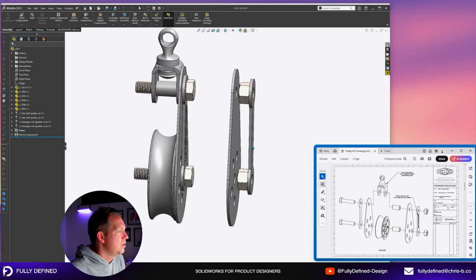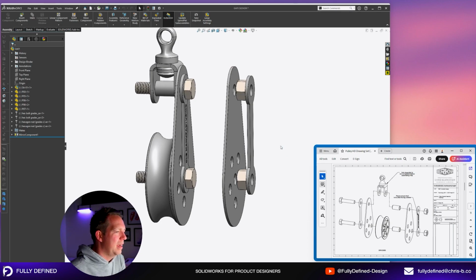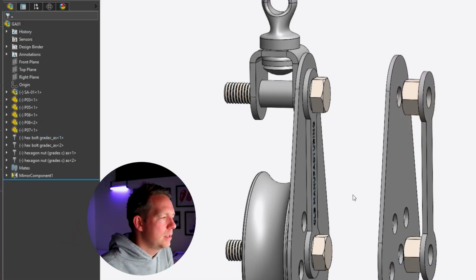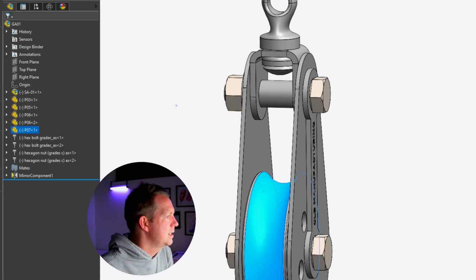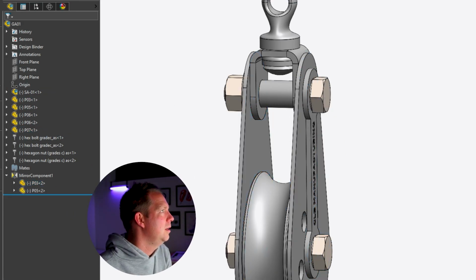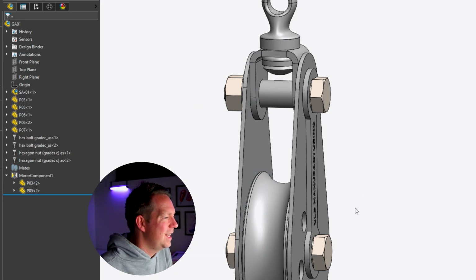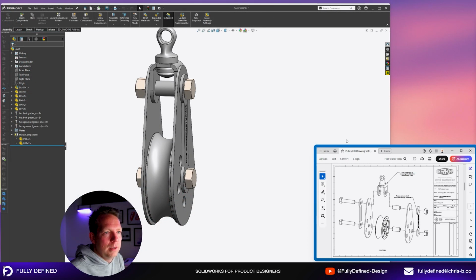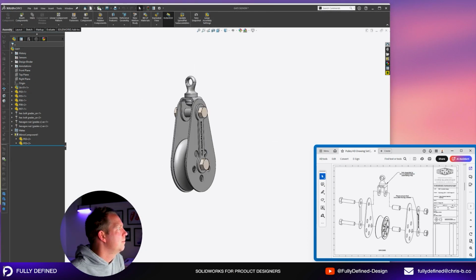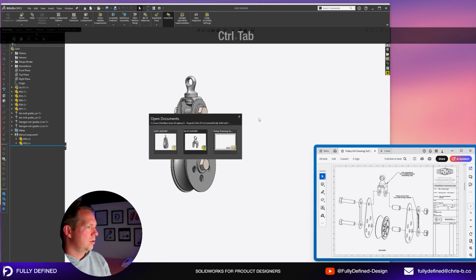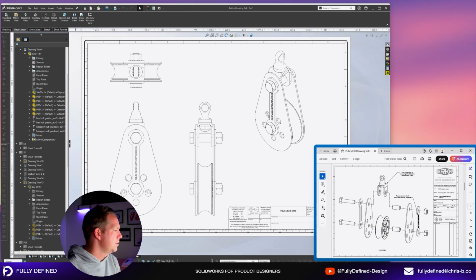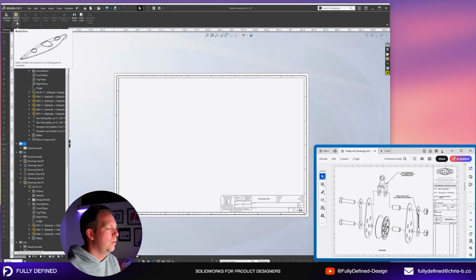So one thing, when you're doing exploded views and then you exit the exploded view, sometimes your parts look all underdefined. It's not true. If you try and click and drag something or press Control B or rebuild, often they'll rebuild to the right position. You can see here it's actually fixed up whatever funny stuff was happening, and it's put it back in the right place. So look, everything looks okay. We're going to save, and then we're going to go Control Tab back to our drawing view. We'll go onto that page for exploded view, and we're going to add a view in.